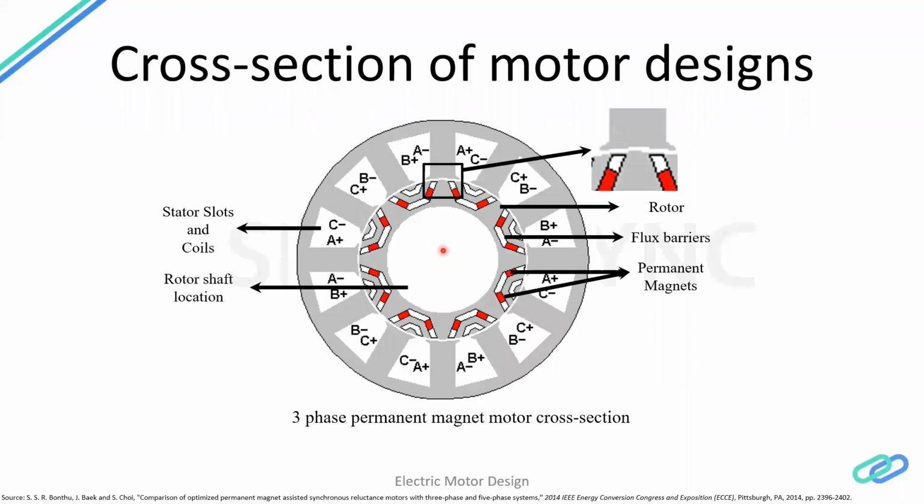The other most important thing is the air gap. An electric motor is essentially a kind of transformer, so the air gap plays a really important role in determining how the flux is flowing between stator and rotor. Optimizing the flux barrier end shape, the stator teeth, and the rotor dimensions will play a huge role in determining how your rotor and stator are saturating with magnetic flux density.